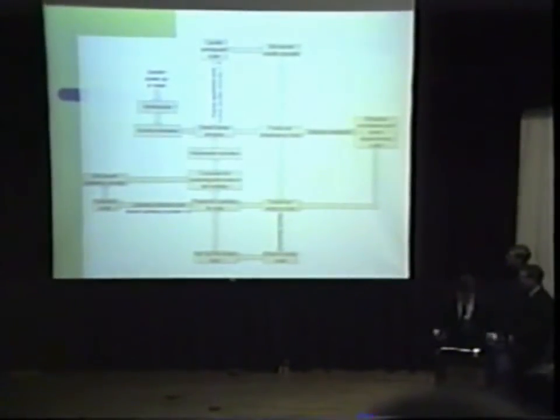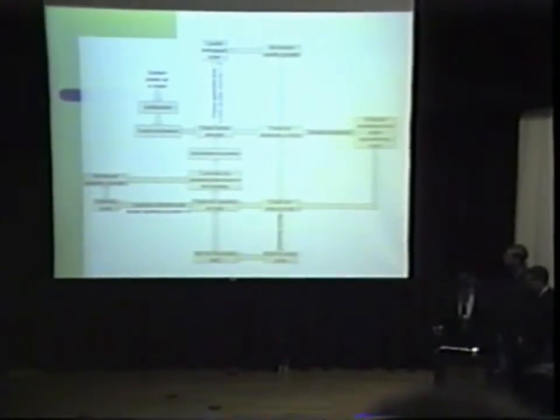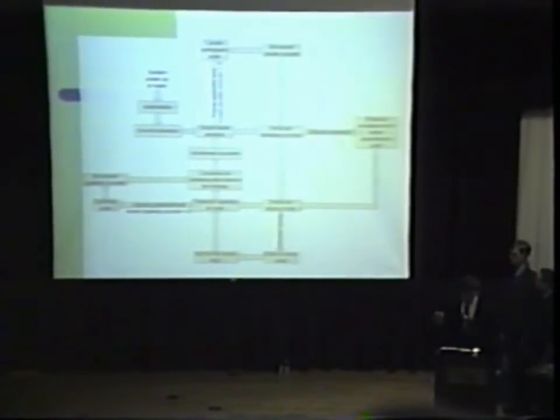The sound activation code simply took the output from the sound activation circuitry, which was an analog signal. It converted that to digital through the ADC, and then compared this value to a threshold value. The basic structure for the code here was a loop which constantly checked to see if it was above the threshold or not.